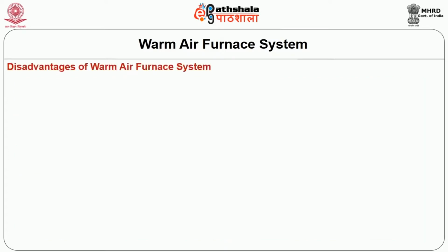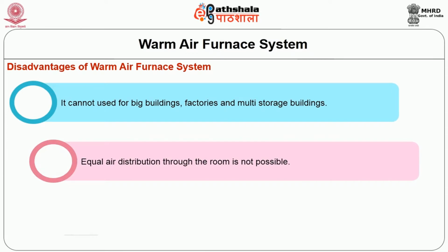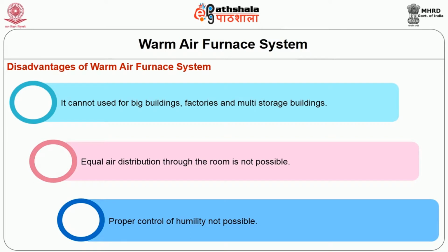Disadvantages of the warm air furnace system. It cannot be used for big buildings, factories and multi-storey buildings. Equal air distribution through the room is not possible. Proper control of humidity is not possible.